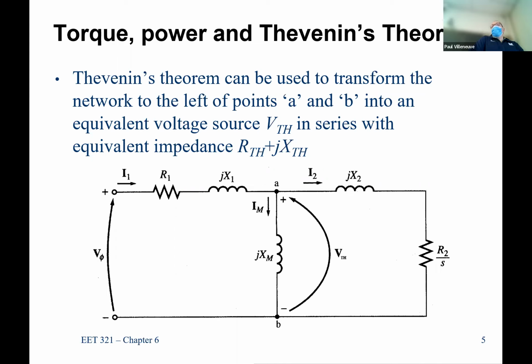In induction machines, as we move more and more into power electronics, they're getting cheaper and easier to manufacture. You can actually use power electronics to increase your load. You basically are increasing the synchronous speed to get more load. What I mean by that is, we said that we have 60 hertz, 1800 RPM, 3600 RPM, et cetera. There's nothing saying the frequency of the motor can't be higher.